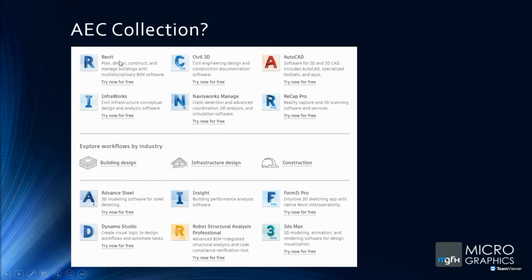It's where everybody collaborates with each other: the architects, the structural engineers, the mechanical engineers, everybody collaborates in Revit, and these models are federated. Typically you'll find that it is brought into Navisworks Manage for clash detection, advanced coordination, 5D analysis and so on. Navisworks handles these large files very easily. There are also online BIM 360 workflows, which are essentially the equivalent of Dropbox, but much more secure in the sense that the transactions are managed in a different way than, say, Dropbox or VPN. It's also the only platform that allows you to collaborate in real time. So that's really just the BIM side of things.